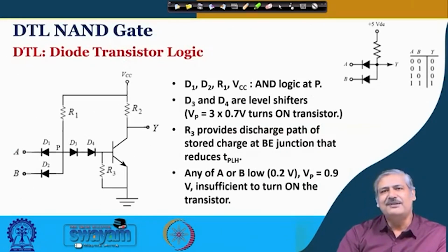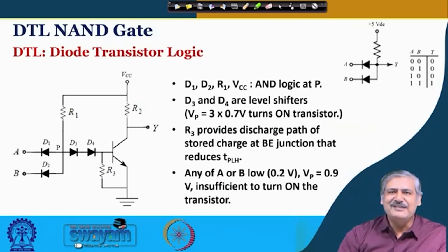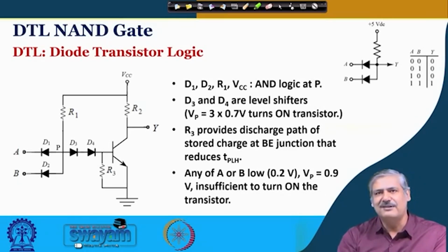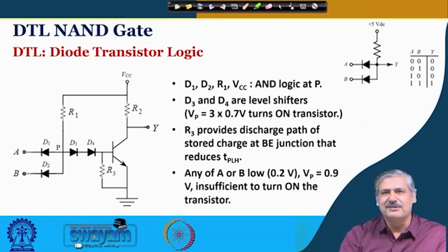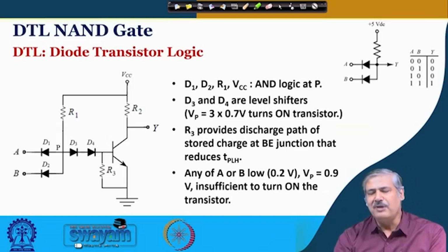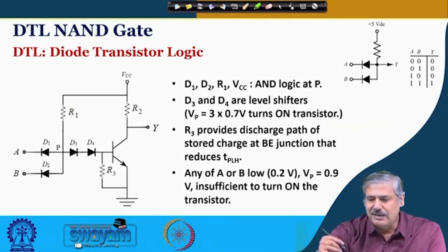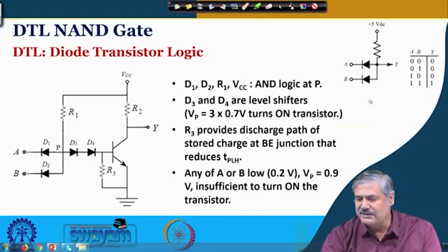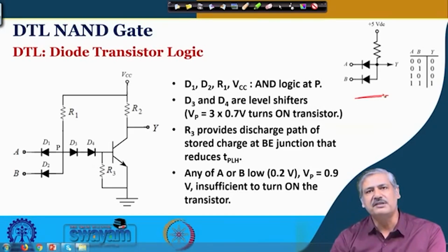Now, to go to transistor logic, let us have a look at something that was intermediate. This was called diode transistor logic. Okay. It does not mean that resistance was not used, but just to keep these 3 letters. So, earlier was resistor transistor logic, this is diode transistor logic. So, the transistor remains, because that only provides the inverter action, the NOT action. And regarding use of diode, we have already seen diode as a switch in our first class, lecture 1. There we had seen this diode resistance combination, right.